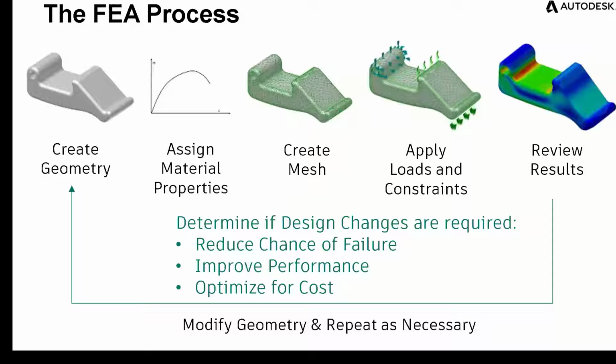Next, you're going to apply your loads and constraints. So what kind of constraints are we talking about here? What kind of operational conditions are we dealing with? How is this face held in place? Is it welded? Is it bolted? Is another piece holding that in place? So that's where you've got assemblies with contacts. And what kind of loading situation? Are you applying a load in one direction versus another direction, or does it have a multi-directional load vector? Get into those situations. Once all of that is set up properly, you run your analysis and you review results.